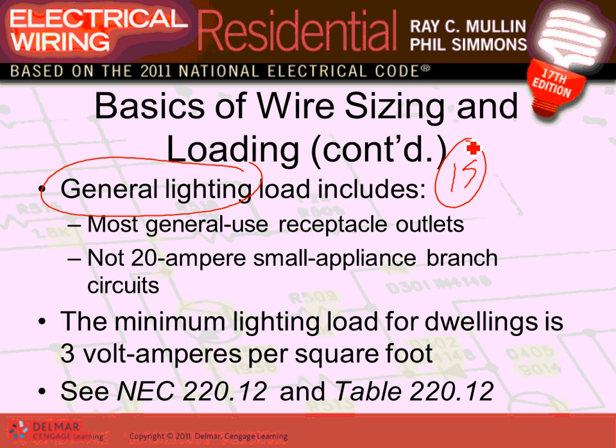When you do load calculation, which is coming soon, to find what size of service you need, the NEC code book does require you to take 3 volt-amps times the square foot of the building to size the panel.